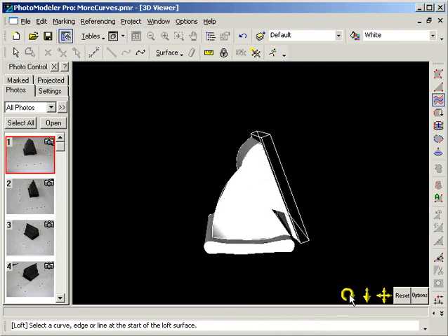As we review this side of the surface, we can see a problem in that some sections of the model are not covered by surfaces. This surface, which is created from these two curves, does not extend all the way to the front. This is because this curve ends at this location, and the surface that we use implies the third edge by assuming a straight line between these 2 points. There's a trick we can use to fix this.